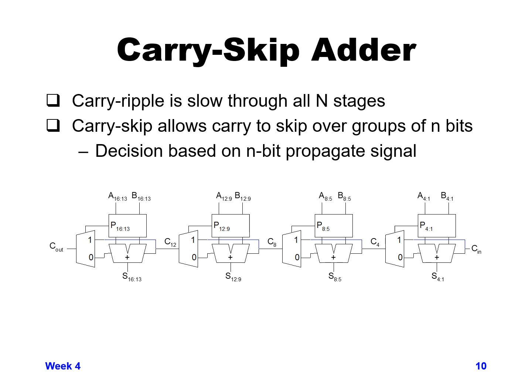All of our propagate values, so propagate 4 through 1, can be calculated just based on bits A and B for 4 through 1. Propagate 8 through 5 is based only on the A and B values of 8 through 5, etc., all the way up to 16 through 13. Each group of 4 can generate a propagate based on that.